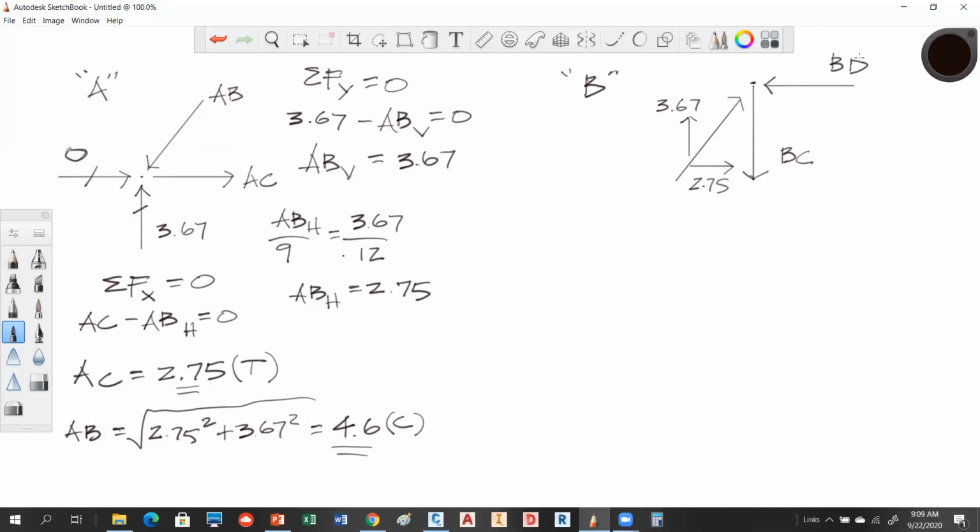Let's stop and talk about this and see if there's any questions. Did anybody see what I did there? Or why I did it? We solved AB. We solved it as compression. When we brought it over here, we brought it in as compression. And notice which way we're acting. Vertical with vertical, horizontal with horizontal. Another common mistake is that you put this one up here and that one down there. If you do that, obviously you've blown the problem, okay?